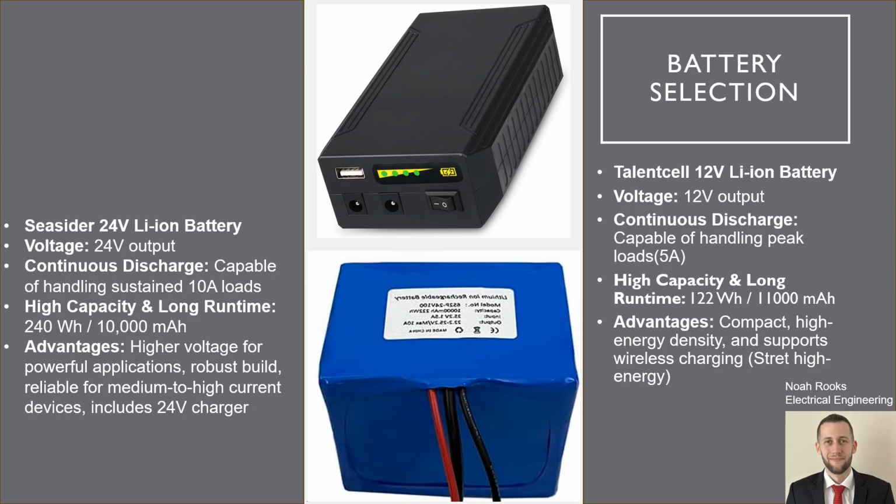The change in motors made us need to increase up to a 12-volt battery, changing our selection to the Talentcell 12-volt lithium-ion battery, which offers 11,000 milliampere hours. This battery supplies a stable 12-volt output that directly powers our motors, while also providing ample capacity to ensure that we get at least 2.5 hours of operation.